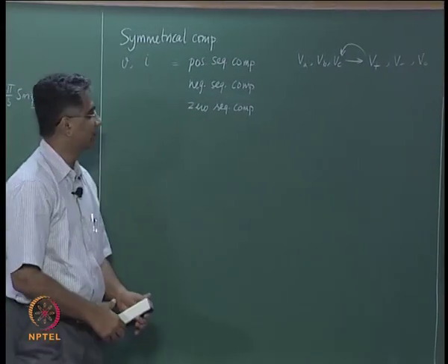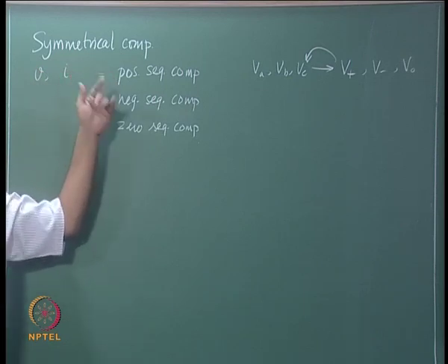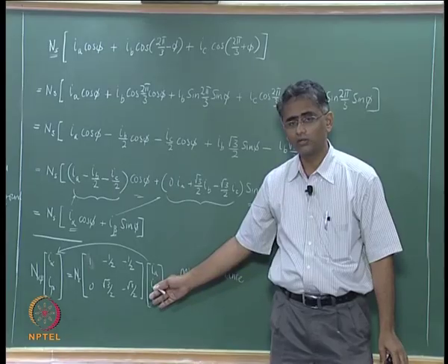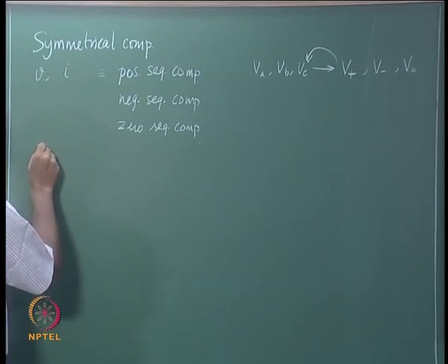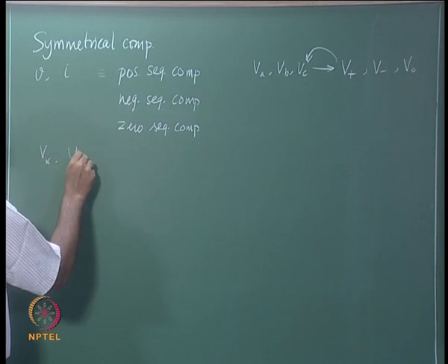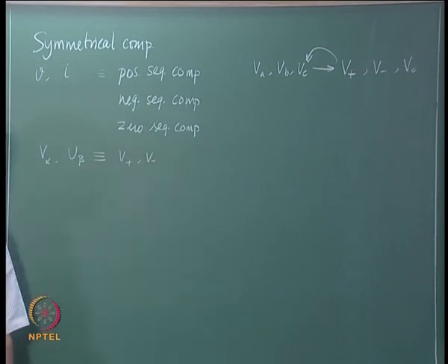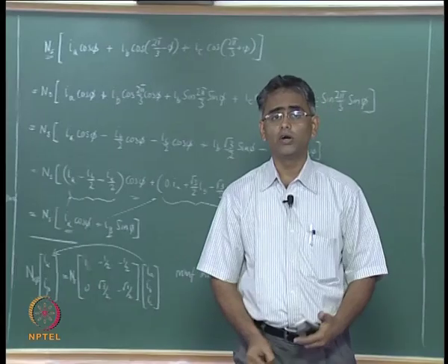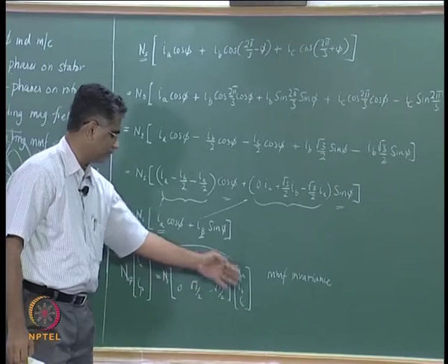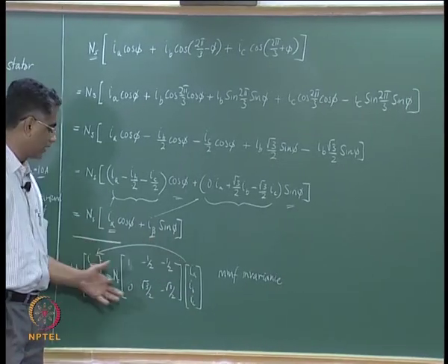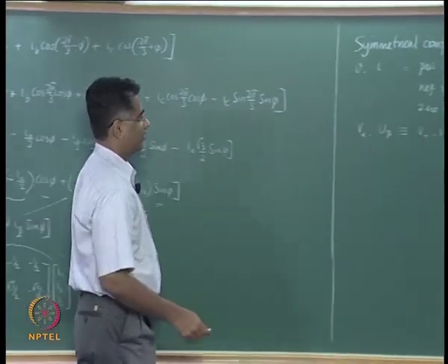What can be shown is, if you look at the equations deriving these expressions, and if you look at the equations we have written here, one can show that if you know V alpha and V beta, it is equivalent to knowing V plus and V minus, and therefore if you want to do the transformation from here to here, or you want to go back, in order to make this description square, the information that is missing is that of V0.